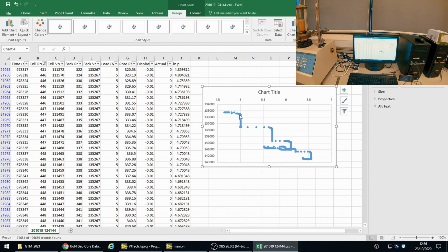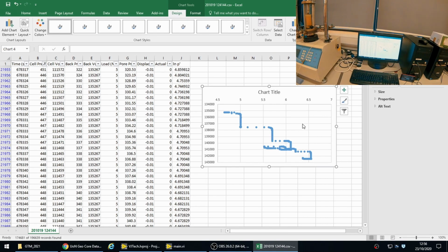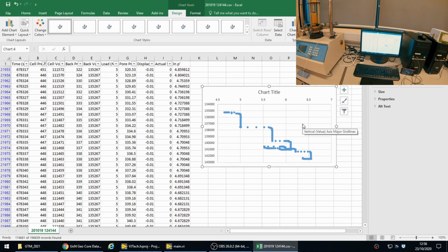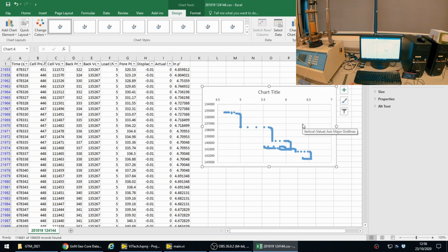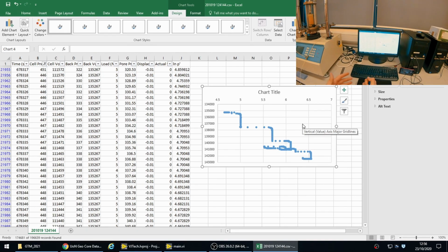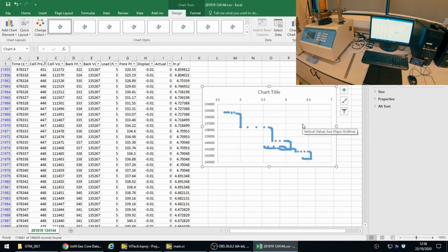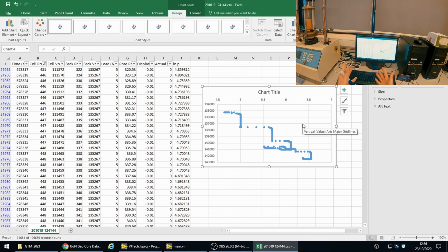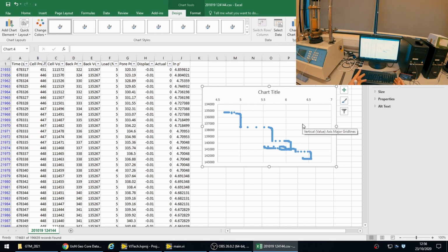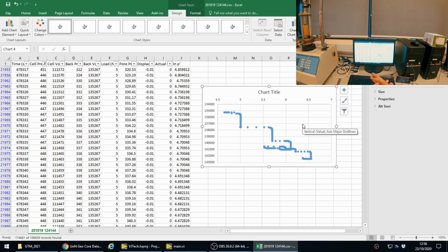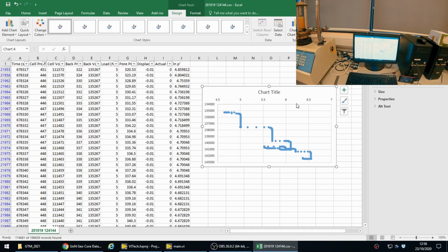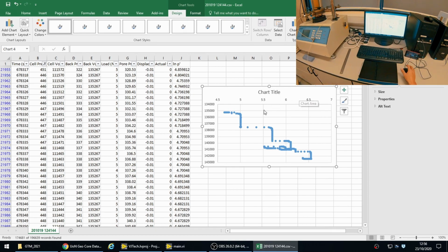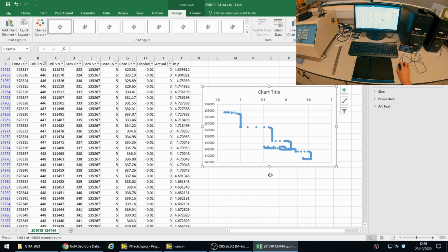You could take the correct values from this to plot your lambda and your kappa lines, which is what you'll need to do for the consolidation phase on your coursework, or if you were doing the coursework for geotechnical modelling, or if you're just plotting the behaviour, if you're doing some soil testing, you wanted to see how your consolidation behaviour looks, and start to think of your material properties of lambda and kappa.